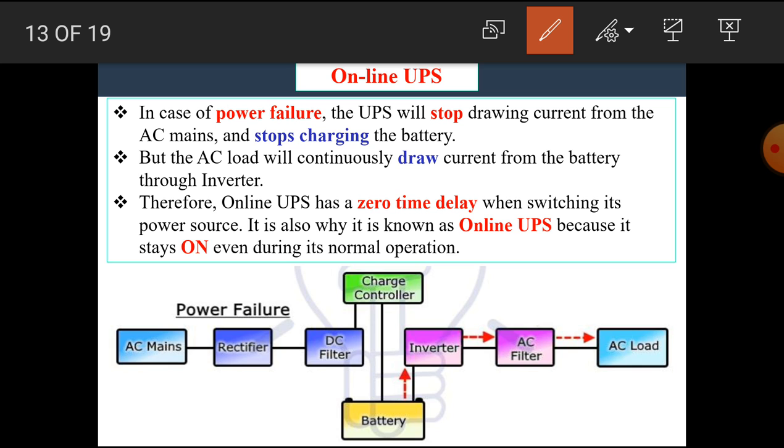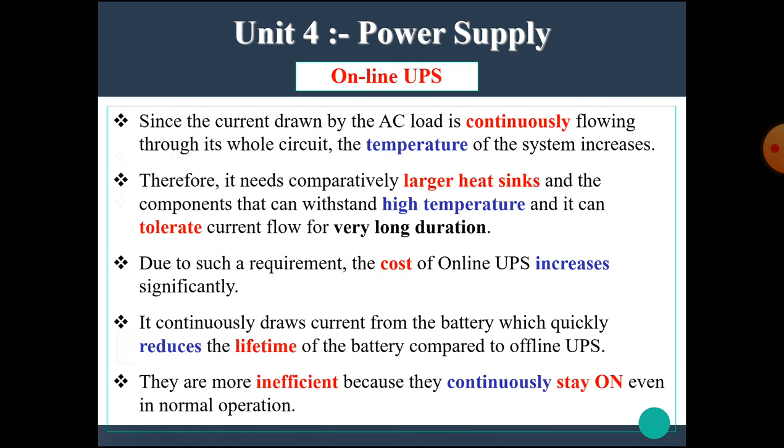That means when the power cuts or fails, the charging of the battery stops, but the AC load draws current from the battery through the inverter and AC filter.